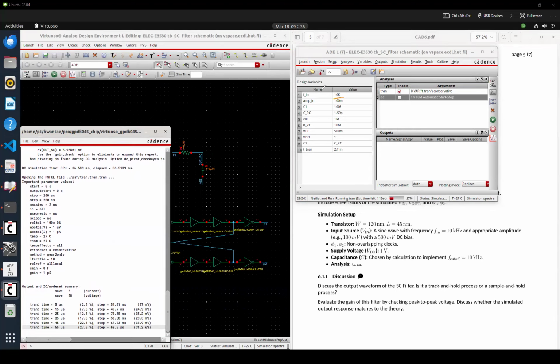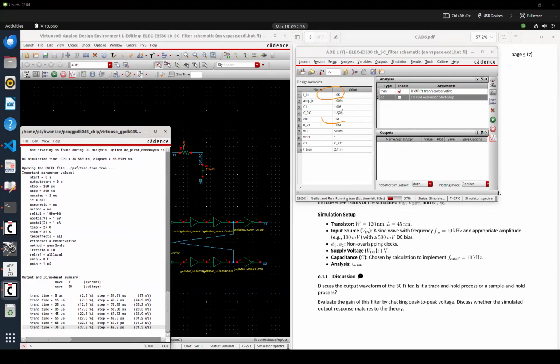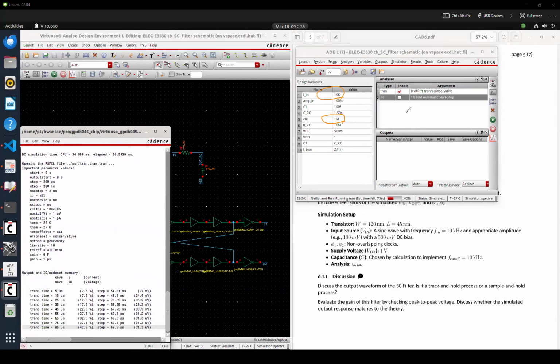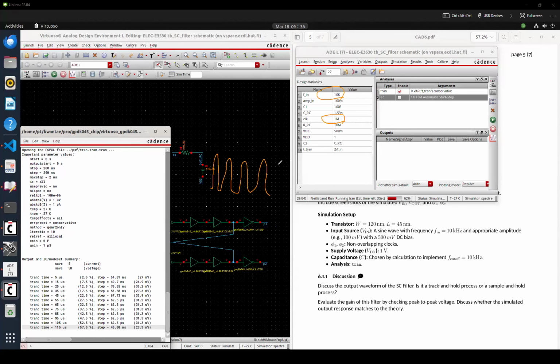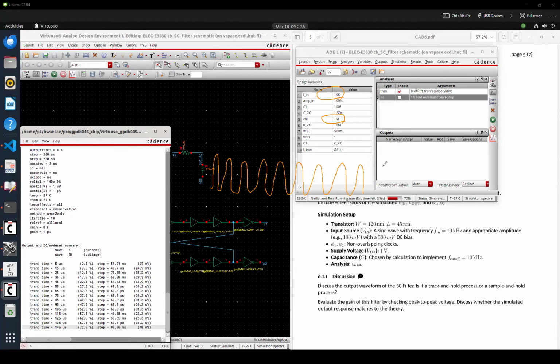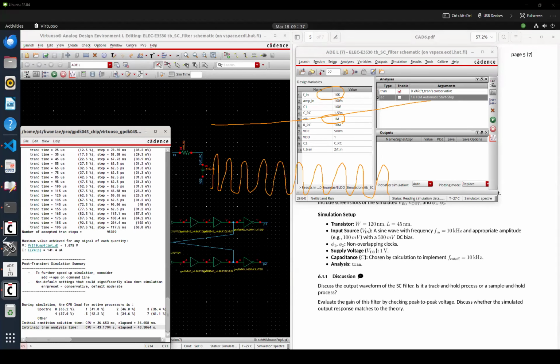difference between 10 kilohertz and the 1 megahertz clock, which is 100 times difference. So this simulation setup is measuring all the transitions of the clock. The data are all saved for all the 1 megahertz clock transitions, but our F_in is 100 times slower. So this is the reason why the simulation speed is quite low. I mean, slow.